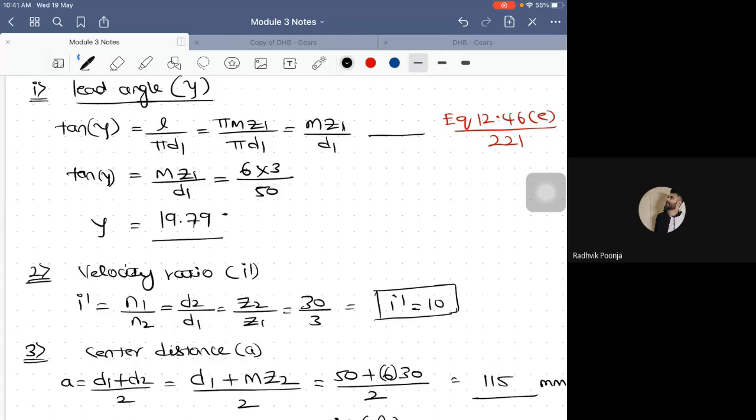Now just go with this particular formula: efficiency of the worm gearing, eta. Do you have any formula? Just check your data handbook and let me know. Something that would be written as Barr's formula. So the formula through which you can calculate your efficiency is given by Barr's, B-A-R-R, Barr's formula. Just check it. Do you have any expression to calculate the value of efficiency of worm gearing?